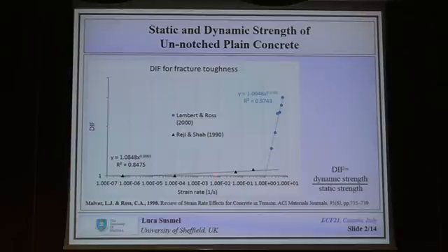And, okay, we also consider the fracture mechanics aspects, so this is the fracture toughness. Surprisingly, we couldn't find a lot of data, but what you can see here is a kind of similar behavior. So there is a kind of knee point, and up to a certain value of the strain rate. And I really don't like this diagram, because what is the strain rate in the vicinity of something which should be, in theory, so sharp to result in a singularity. But, you know, let's take the results as they are presented. And what you can see is that there are basically clearly two regimes. So we started focusing our attention on this initial regime.